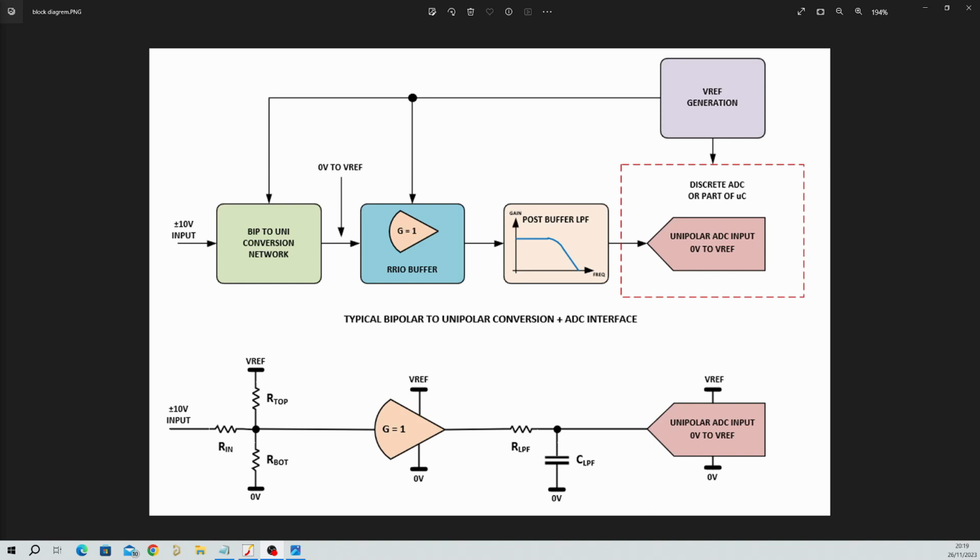So what happens in a capacitive ADC, it'll switch, it'll grab a pulse of current, and sometimes, if you have such a high impedance, you'll get a bit of a droop voltage. So we have a capacitor there that supplies that instantaneous charge, and that helps us maintain accuracy.